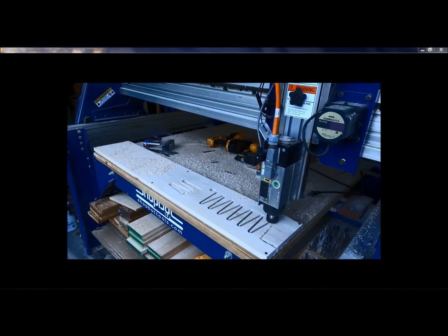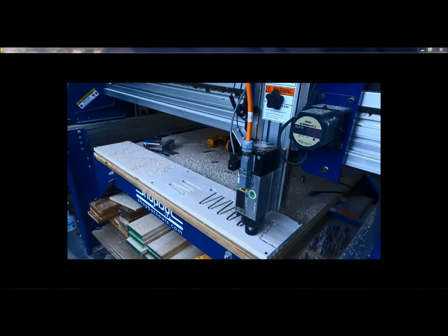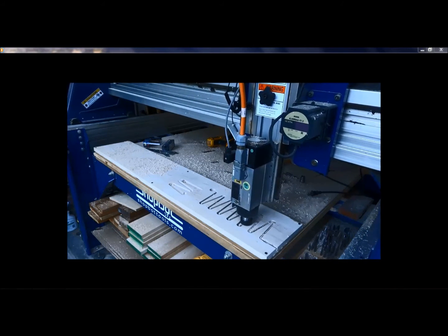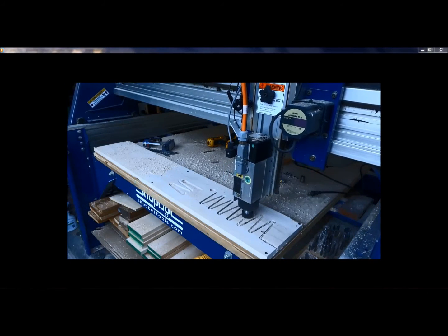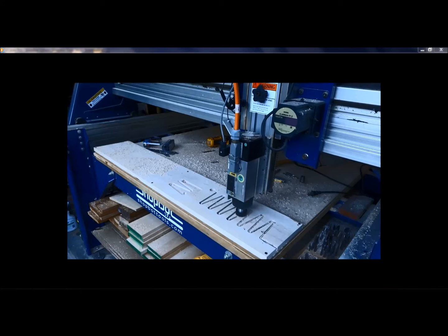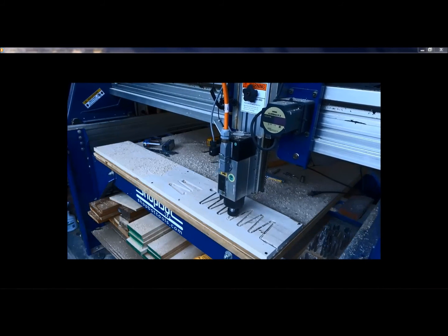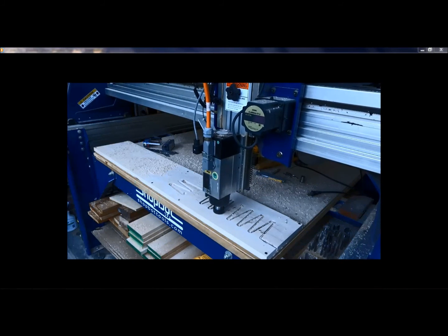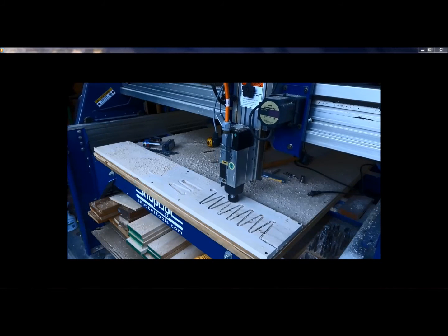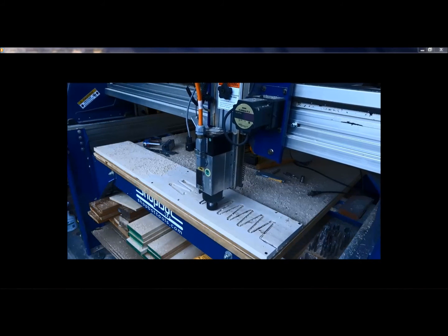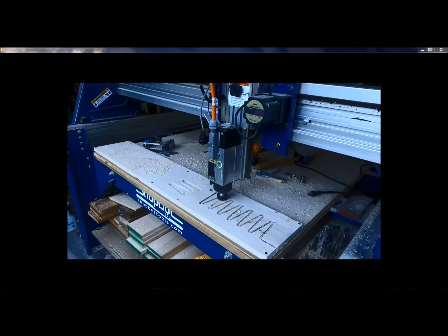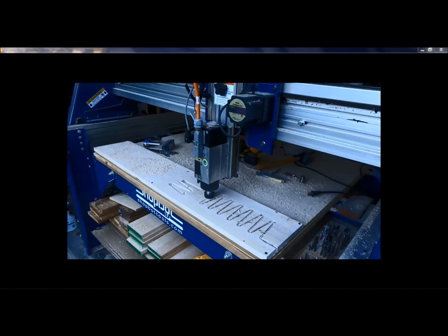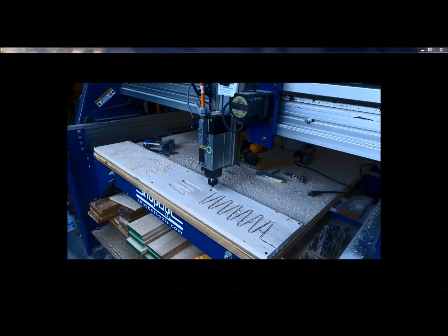For it to have plunged straight down into wood, that would have wrecked that bit or damaged the bit, knocked your spindle out of square, a lot of different things. So that's where a lead in is important when you have certain profile bits. Also, when you want, like the earlier example with the rectangles being cut, just for edge quality. But there's definitely certain bits out there where you have to have a lead in, and in this example also a lead out, which we can't have off the edge of the material, but what we have is a pocketed area already there that is removed that it can go through and then pick back up.